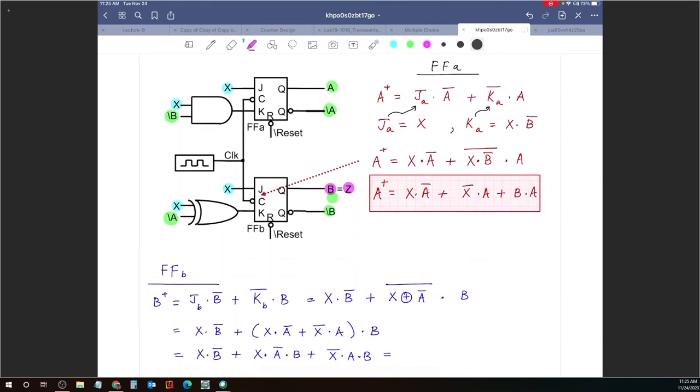All right, I see that there is a B complement. No, there is an X here and here. They both have X, so I can write this as X. Do you still need to complement the exclusive OR part? Yeah, so I did, right? So if you look at this, X exclusive OR A complement, the entire thing complemented, is simply X exclusive OR A.